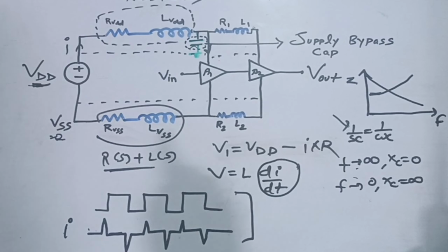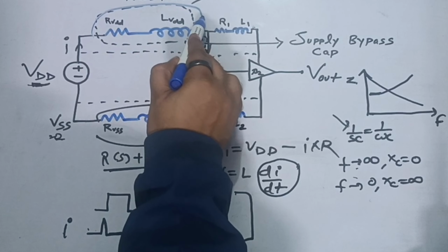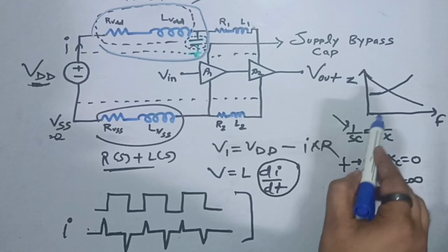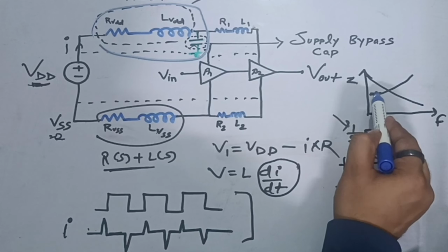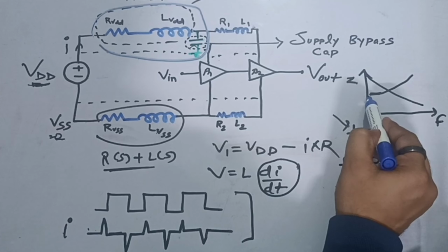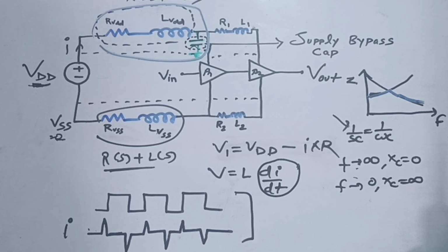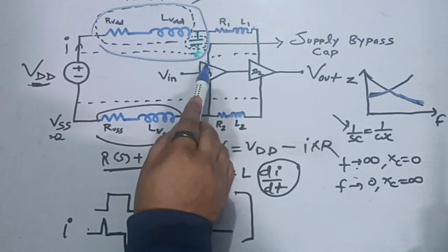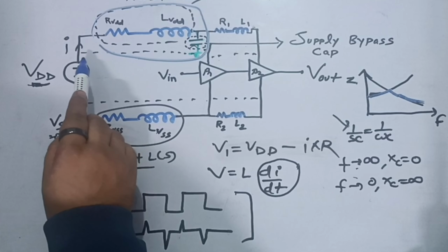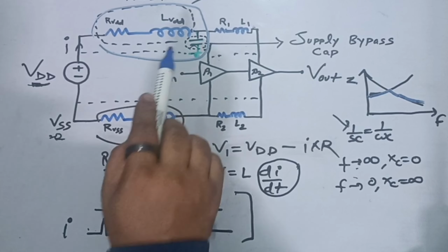So overall, if you see, because of both of these structures, if I talk about this structure only, RLC, combined, both will cancel out each other, and throughout the range of frequency we will get this kind of impedance across the range of frequency. That's what we wanted, to have a low impedance between supply and op-amp's input, so that the whole supply which is applied there can directly be given to the op-amp, and we don't get any disturbed output.